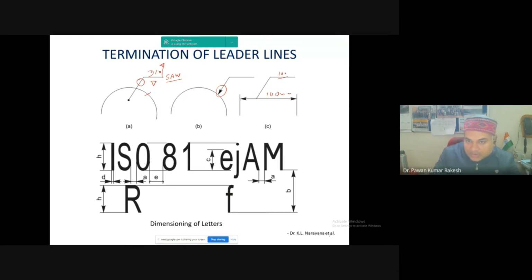In the case of machine drawing parts or in an assembly, multiple lines are coinciding. In that case, if multiple lines are coinciding, you can use extension of the leader line. If there is no space on the machine drawing parts, then you can extend the line and note down the dimensions, or you can note down any of the features.